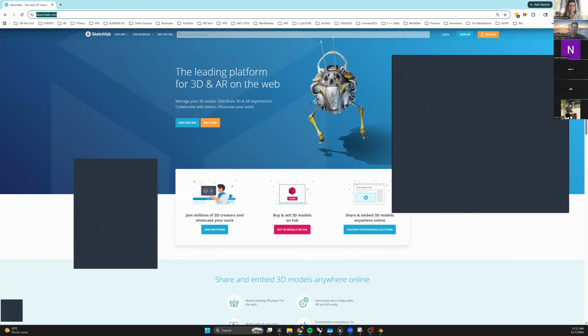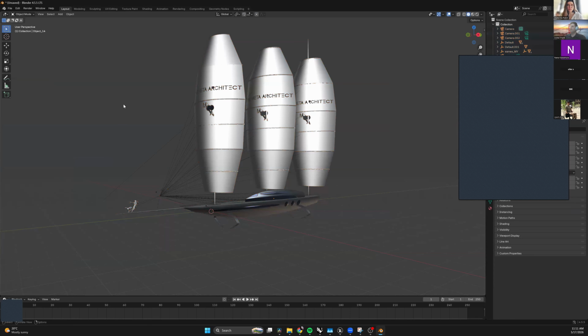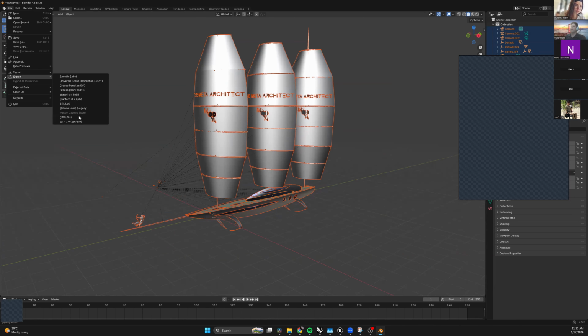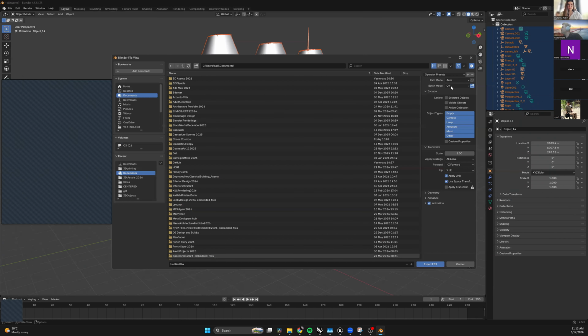Once you've done that, go back to Blender and center it, just like I showed you. This one is a little bit tricky. We have to make sure that the entire model has triangles and that XYZ is set. I'm going to set export to FBX, go to selected objects, and change it from Z forward to X forward, and from Y up to Z up.